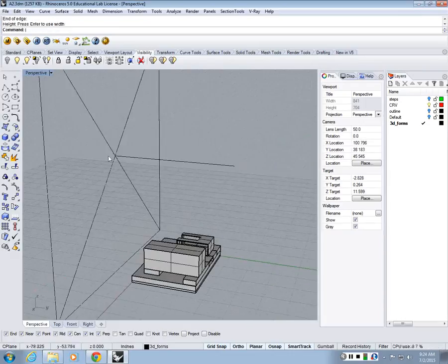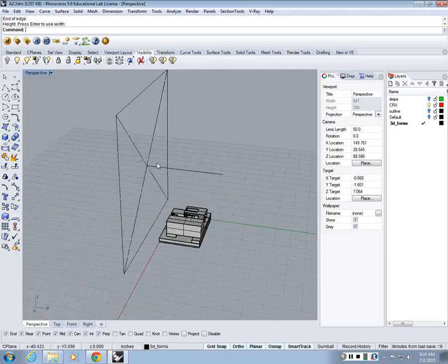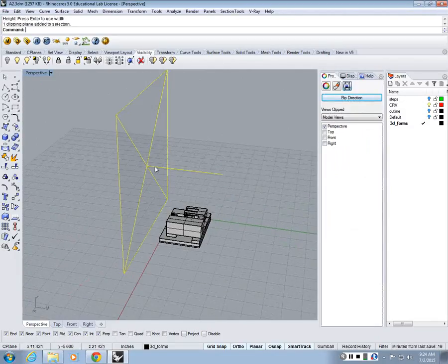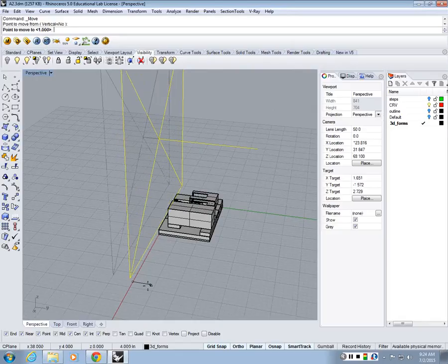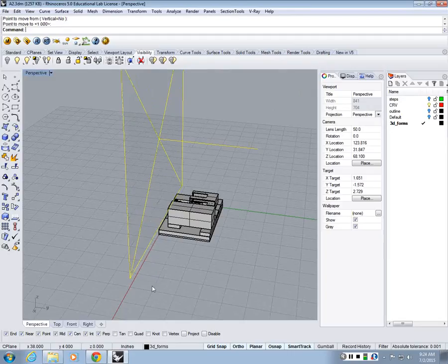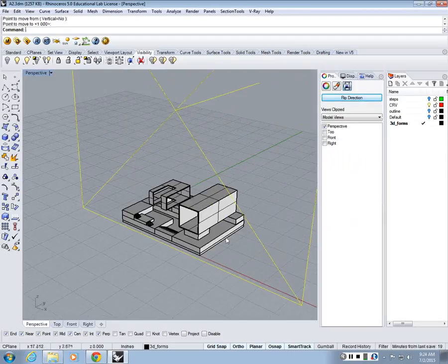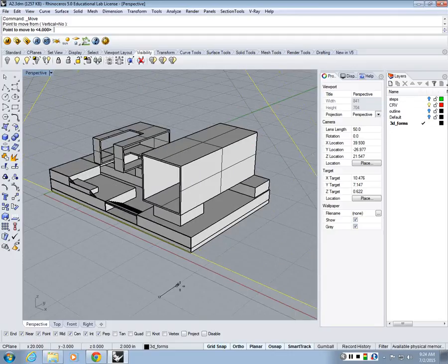And this arrow shows me the visibility side of the clipping plane. So this basically cuts in any solid model in the view and then trims the rest of it. So if I move this towards my model, you're going to see it taking out the solid portion of it, right? And if I move around and look at it from this view and move in, I can actually see how my section is changing.